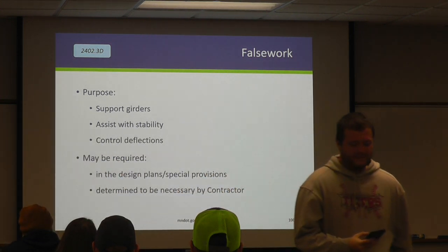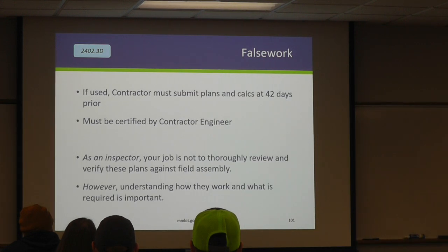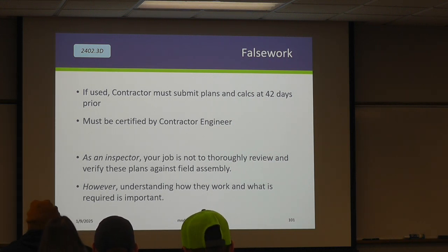You can just place it in appropriate spots. So false work is going to be used. There are some situations where it's required, but if it's going to be used by the contractor, 42 days prior to its installation, they have to submit plans and calcs. These have to be certified by the contractor's engineer. We do require a professional engineer to develop these.